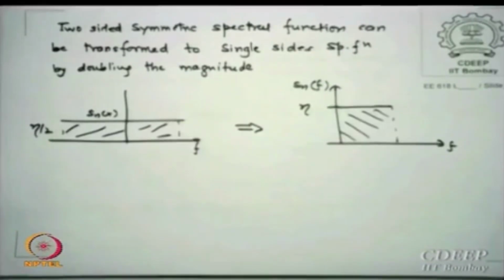A to D converters and D to A converters require noise shaping to the maximum. You may have 1 loop, 2 loop just to shape the noise, so that the signal to noise ratio is very large. There is another term which is called signal to noise distortion ratio or SNDR, which we will cover in a mixed signal course some other time. So noise in analog is a very important parameter, because please remember, if noise is larger, you will require larger power to dissipate. So your first hit will be power dissipation.